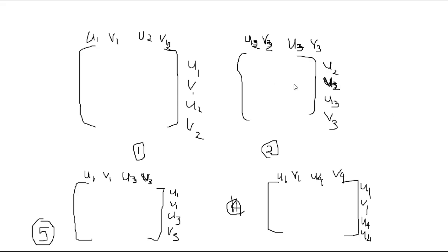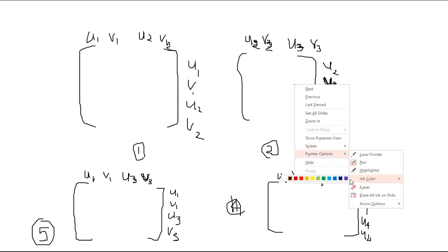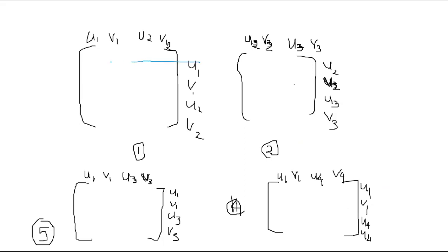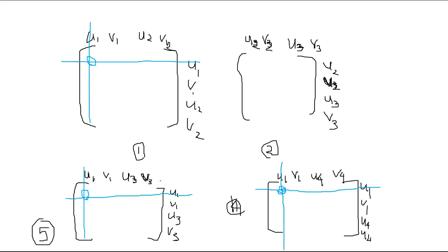Okay, that is also important. U1 row, U1 column, right? Here there is no U1, so no contribution from this member stiffness matrix. There is a contribution from this U1, U1. This element comes. Now remember, AE over L is inside the matrix. I have multiplied everything by that. Don't keep it outside, because we need to simplify that. These three should be added together.